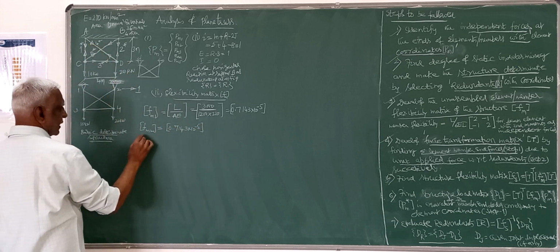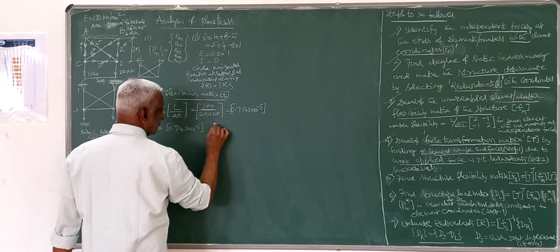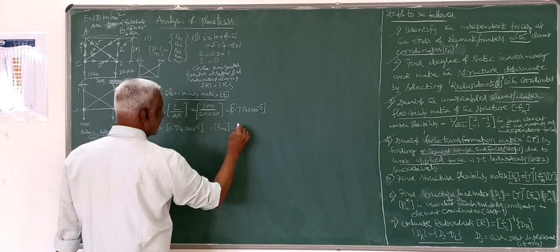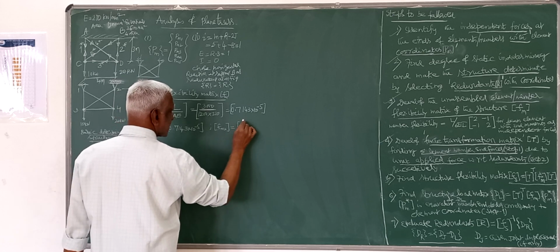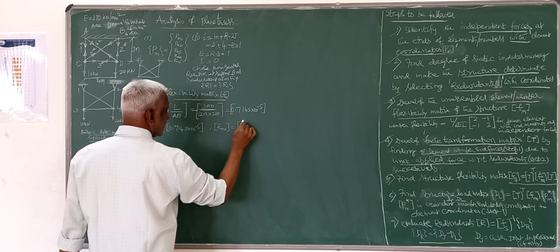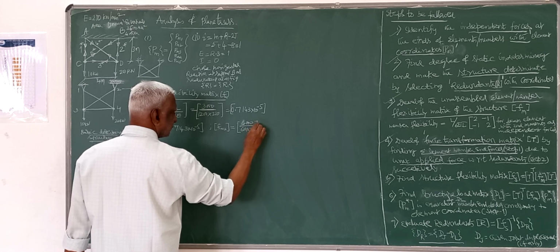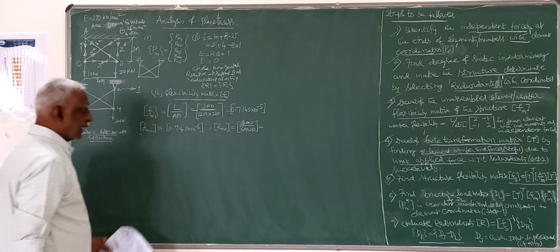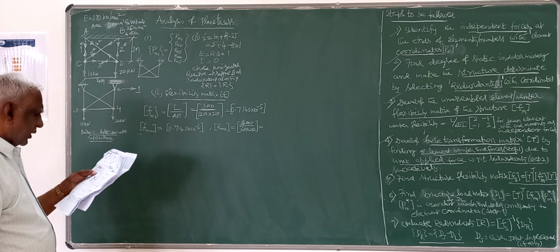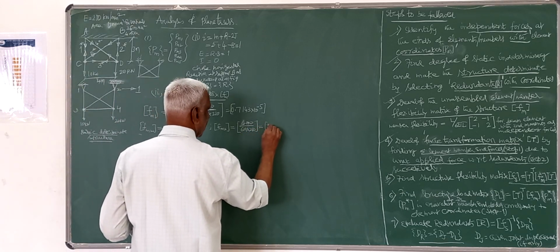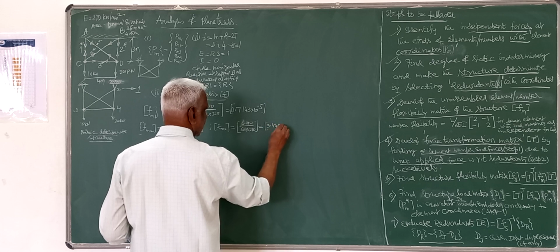And other members on similar lines, member 3, that is horizontal member, length is 4000, area of cross section is 600 into 210. So this you will get as 3.1746 into 10 to the power of -5.